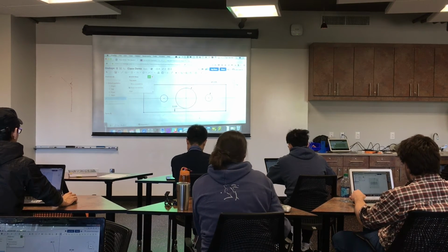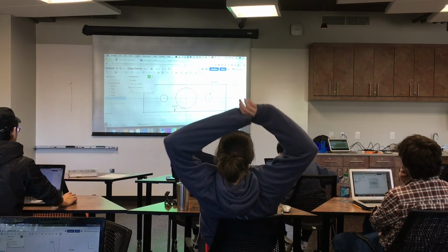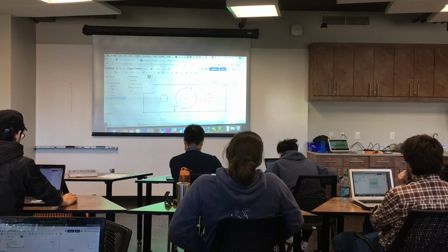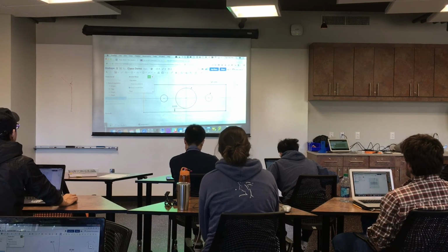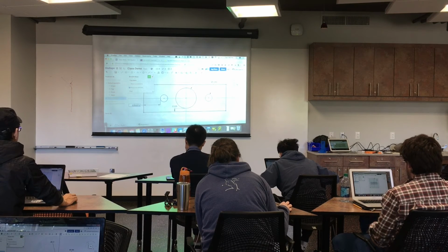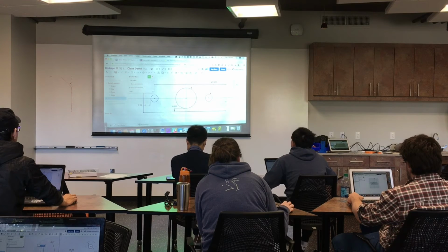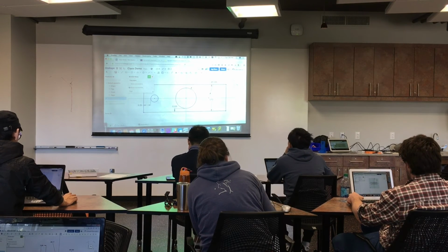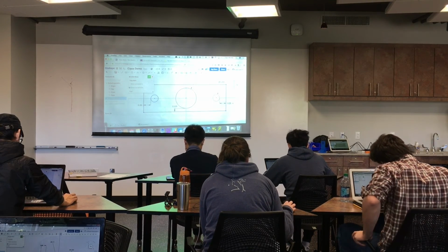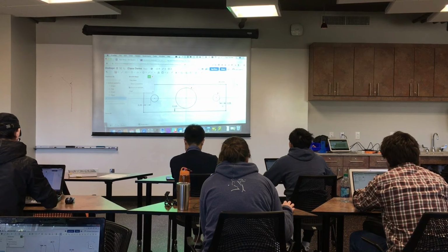And you see that some of the lines have turned black. Like this circle is black, these lines are black. That means they're fully constrained, so we can't drag them around anymore. We're done as far as they're concerned. Let's do the same thing here. Let's say 1/4 of an inch here, and 1/4 of an inch here. Those are somewhat redundant. We could get around that if we wanted to, but for now, we'll call that good enough.